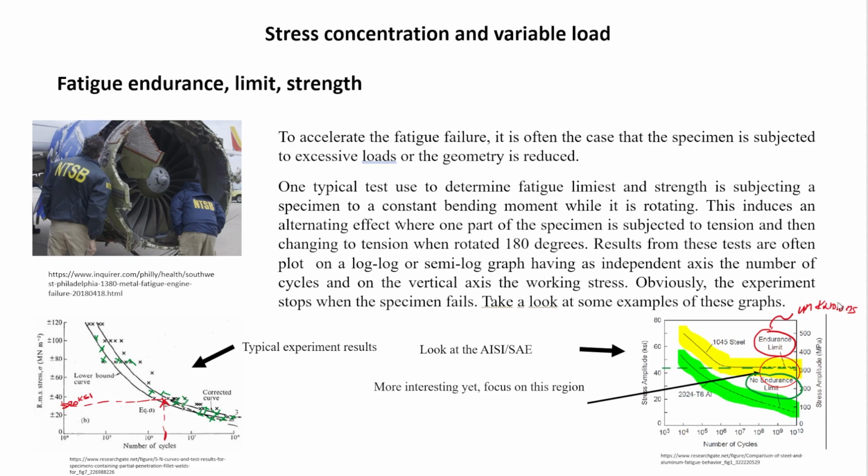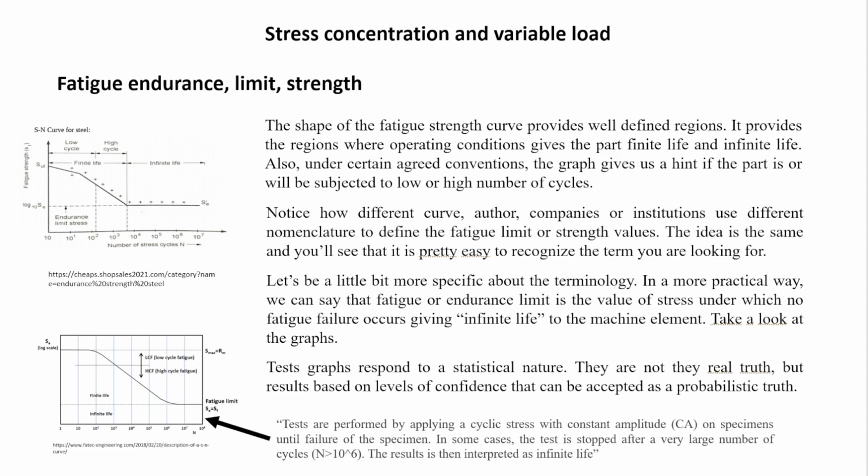And we do that by applying certain factors that we will see later. The materials we're going to use here follow, as I mentioned, this type of shape, where this one here is the endurance limit. Some others are going to have this kind of shape, but it's more or less similar.